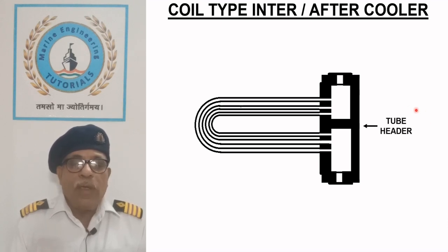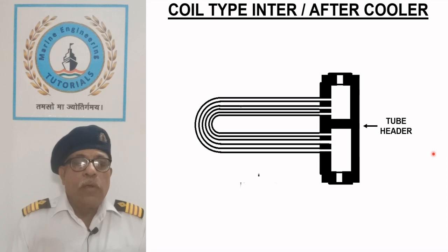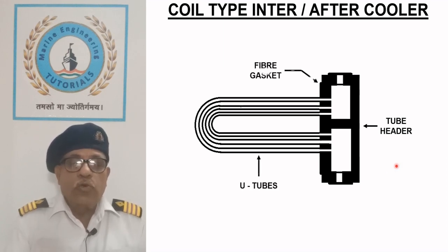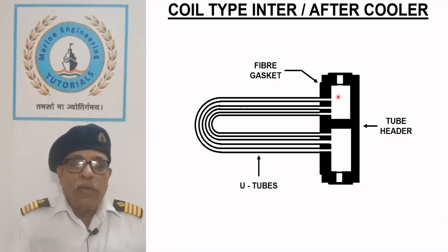It consists of a cast steel tube header. U-tubes are attached to the tube header which automatically compensate for the expansion and contraction. As tube ends are not accessible, their cleaning is carried out chemically.